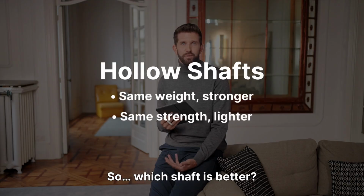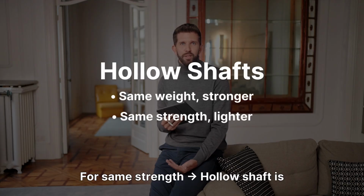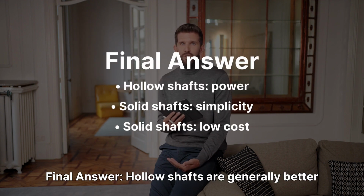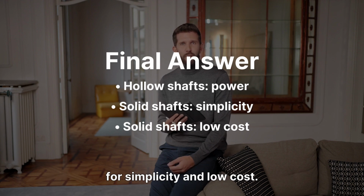So, which shaft is better? For same weight, hollow shaft is stronger. For same strength, hollow shaft is lighter. Final answer: hollow shafts are generally better for power transmission. Solid shafts are preferred for simplicity and low cost.